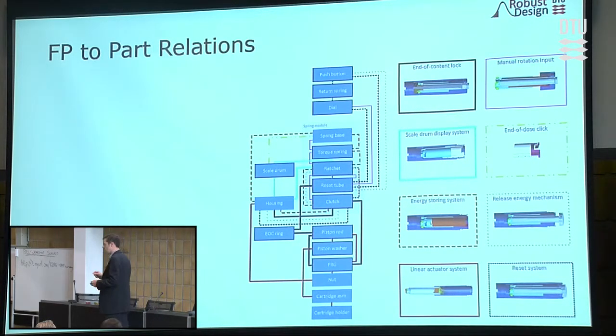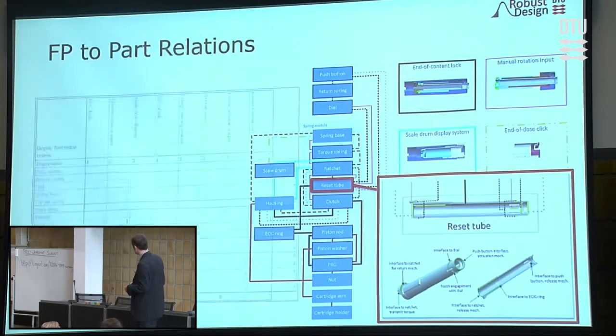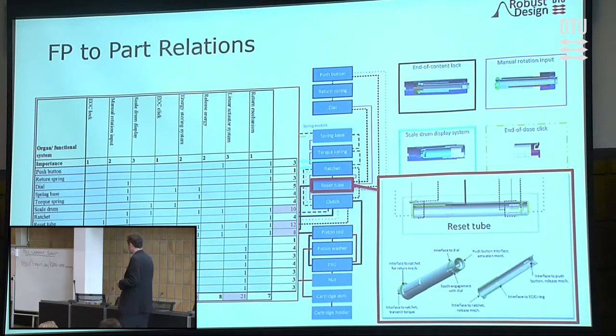So it's not just recording for recording's sake, but when you map these relations, you learn a lot. This is the relation maps between parts and function requirements in one of the injection devices we are working with. And we can see that on a single component, how many functions interact with it and which surfaces. And we can produce a very simple relational matrix here. Now, we don't need to map sensitivity values or any complicated maths here. This is just geometry and our design intent.